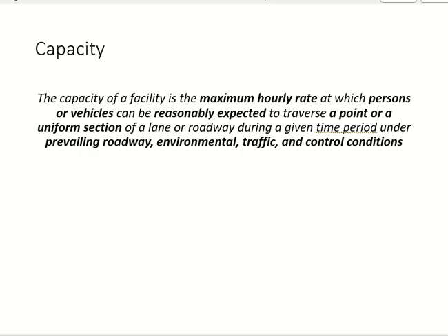I have this point. On this point, the road has X properties. In the next millimeter, the properties change, any property. So the capacity of this point and the next point is not the same. Clear? If properties do not change for 100 meters, capacity is the same for 100 meters. If properties do not change for 1 kilometer, capacity is the same for 1 kilometer. So it could change at every point, or it may not change for a very long distance, depending upon the road properties. What are the things which change the capacity? First thing is the road itself.